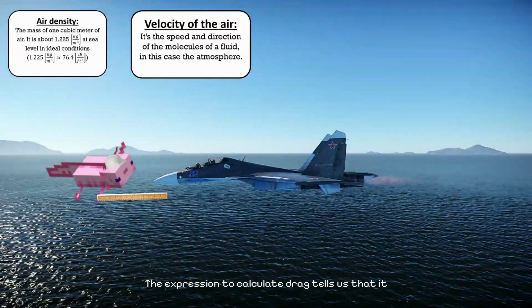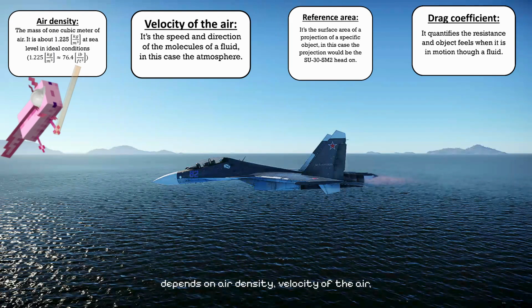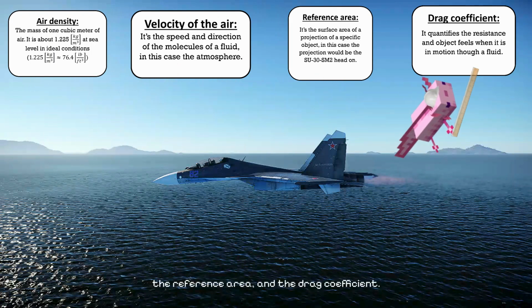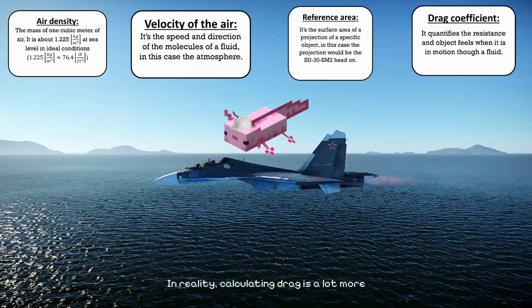The expression to calculate drag tells us that it depends on air density, velocity of the air, the reference area, and the drag coefficient. In reality, calculating drag is a lot more complicated than just one single formula, especially when the aircraft approaches or exceeds the speed of sound. It is a process that involves a lot of simulations. But for simplicity's sake, we'll assume that this formula applies for any speed.